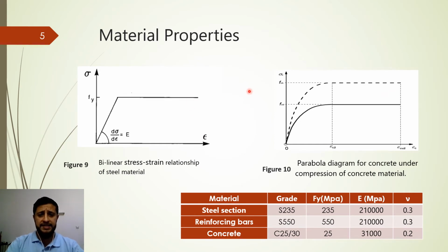Material properties. The steel is supposed to behave as an elastoplastic material, defined as elastic, perfectly plastic, as shown in figure 9. Figure 10 shows the stress-strain relationship of the concrete. Steel and concrete properties specified in ANSYS contain a Young's modulus, Poisson ratio, and yield strength. This table describes the specific properties utilized in this numerical modeling.